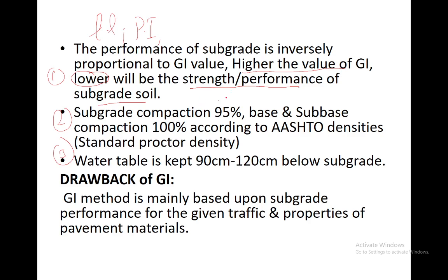The subgrade is also compacted to 95% and the subbase is compacted up to 100% of their AASHTO density according to the standard Proctor test.